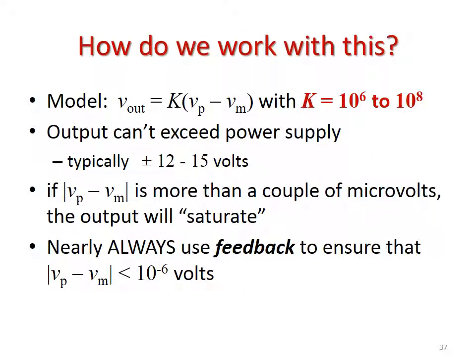So how do we work with gains that are this high? Usually we include a feedback source so that we don't saturate the output. A feedback source allows us to get a gain a lot lower than that K value, which is the ultimate gain. So we're trying to stay with a smaller gain because that way we can work with it. We can use it and process it a little bit cleaner than if we just throw all of our power on or all of our power off.